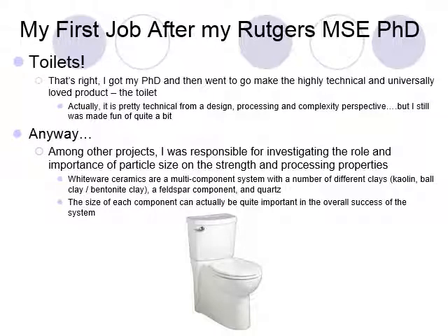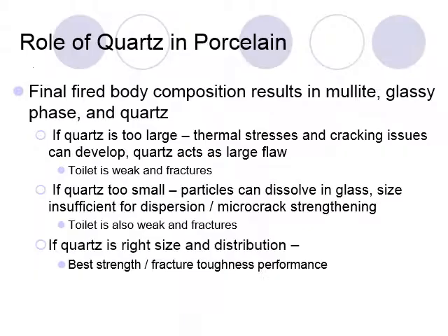After getting my PhD from Rutgers, one of my first jobs was to work on toilets. Not very high-tech or exciting as you would think, but there is a lot of complexity and design related to it. One of the projects I had to work on there was discussing the strength properties of a certain toilet that was wall-mounted. What was discovered through the work was that the component size of the ingredients that go into the kaolin and the rest of the system, the clays, the ball clay, the feldspar, and most importantly the quartz, the size of the components and the particle size control really did affect the strength of the system.